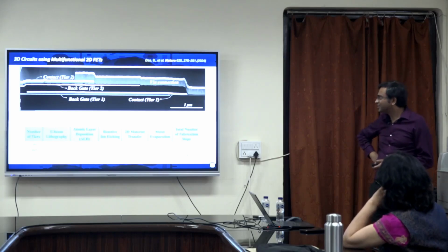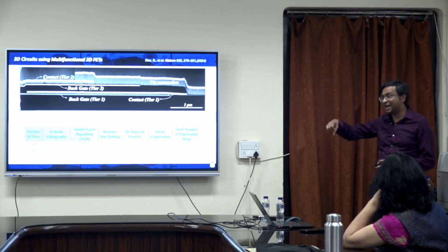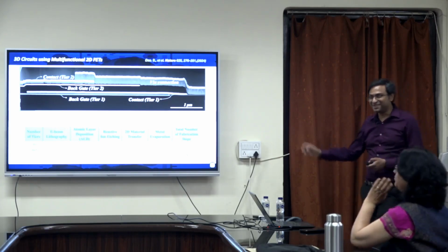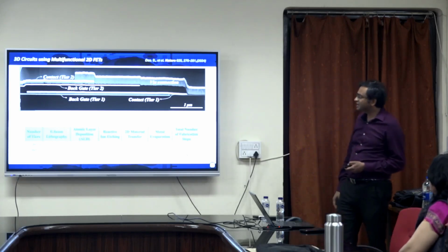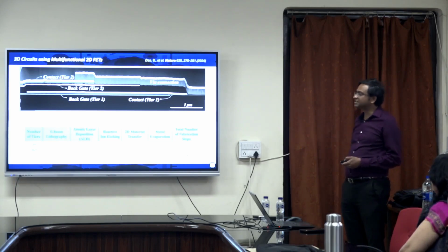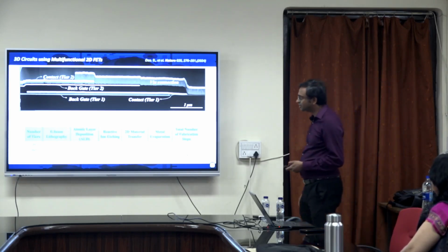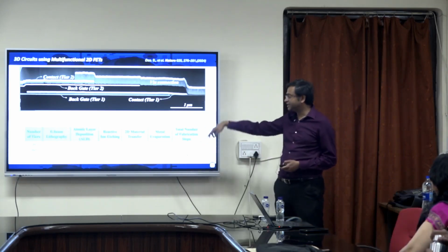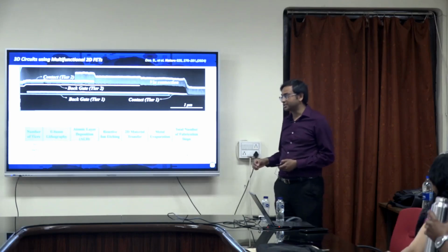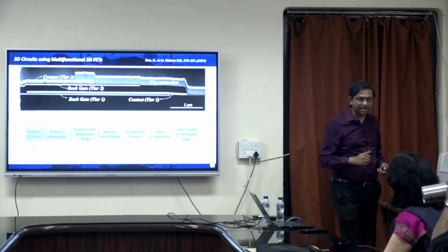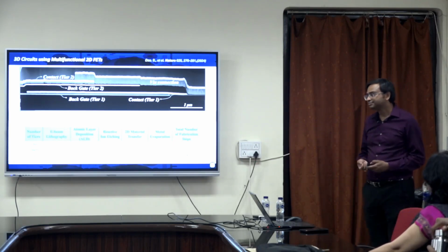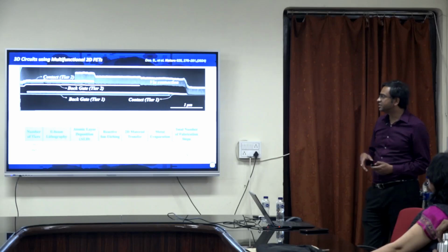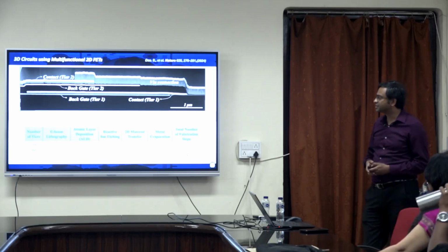I was telling them, the tap is open, and not water, money is flowing when we start making these chips. Not all the oxides, the gate oxides are deposited using atomic layer deposition. And then the intertier dielectric is done by e-beam evaporation, because that doesn't have to be extremely high quality, and if you do it using ALD, it will just take a long time. So we don't do ALD for the intertier dielectric, we do just e-beam evaporation.